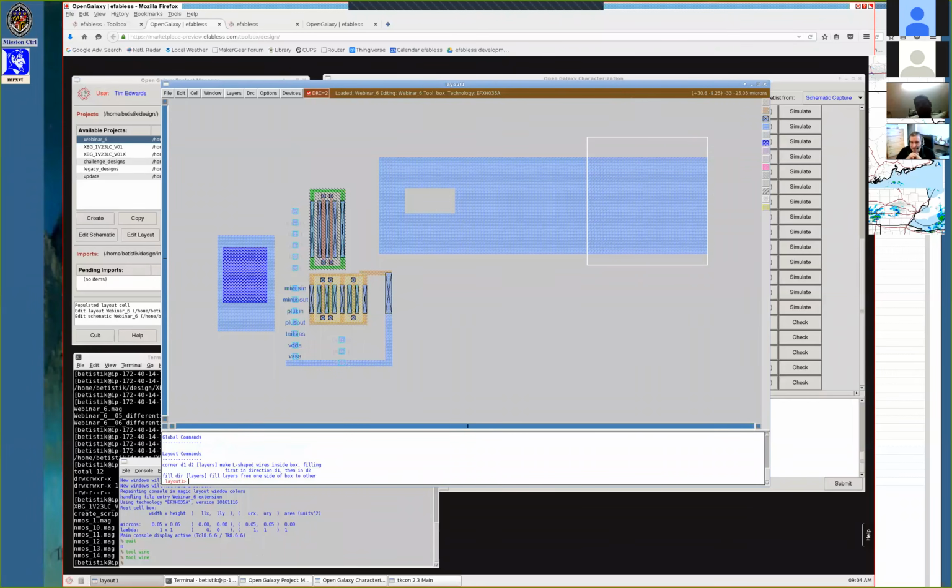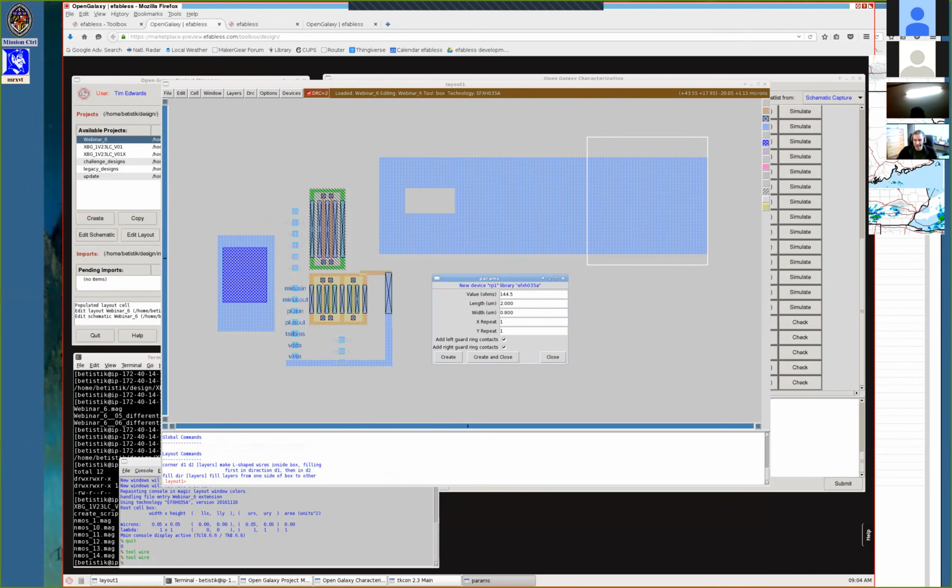But for instance, having noted that there are some designs out there that have very, very long resistors on the order of mega ohms, your circuit might be one of those. Yes, the device for, say, the RP1 resistor is maybe particularly large and very difficult to make at that size. And what works better in those cases is a snaked resistor. Yes, so I promise I will try to work up a snake resistor type in the PDK to facilitate that.